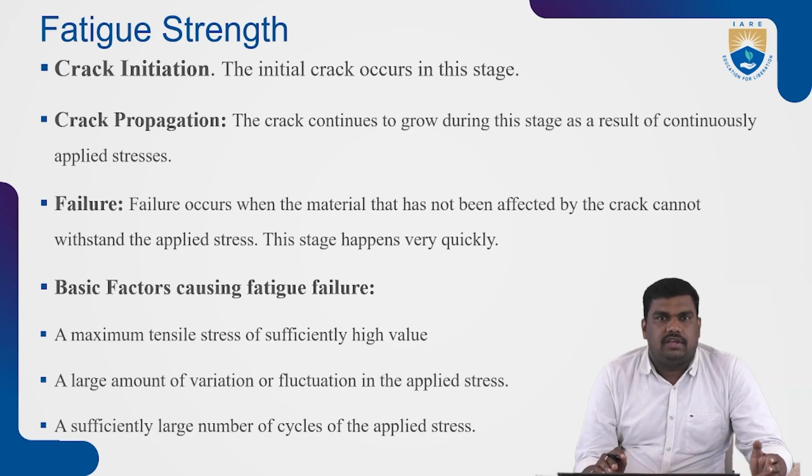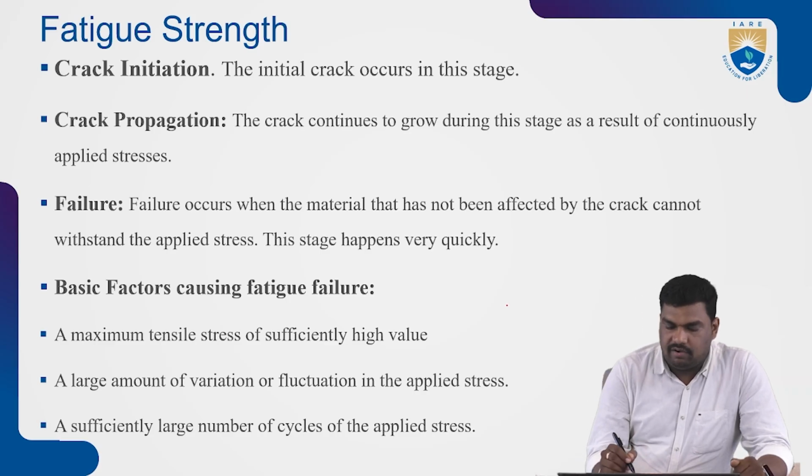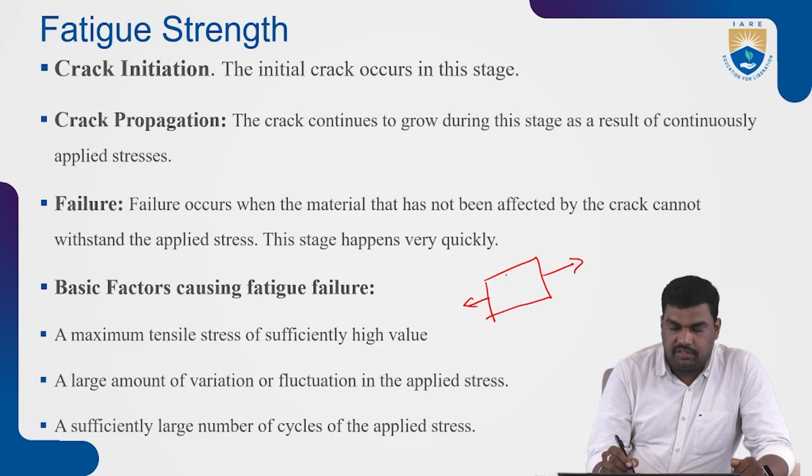Today we are going to see the factors affecting the fatigue strength. The first is the surface condition. Surface condition means any undulations, scratches, or notches on the surface. When any load is acting, the stress creates resistive forces. Stress always travels in a straight path.